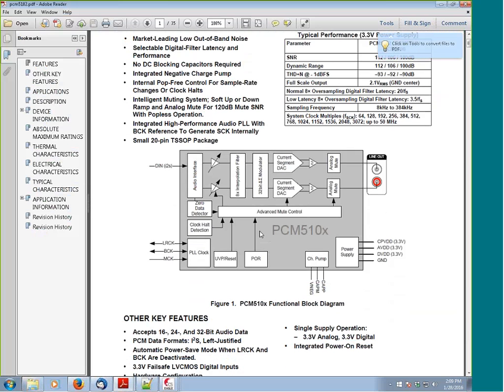The audio of the Beaglebone Black, as you guys know, if you do have the Beaglebone Black, it doesn't have an audio output built in. What it has is a couple of streams, a couple of interfaces that can be used to output audio. In my case, I'm using the HDMI audio, which is output through an I2S stream. And that's exactly what this chip takes.